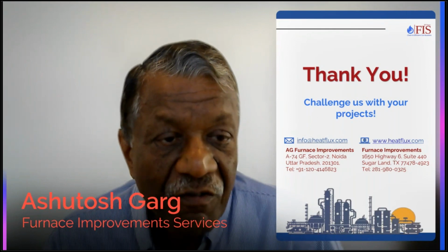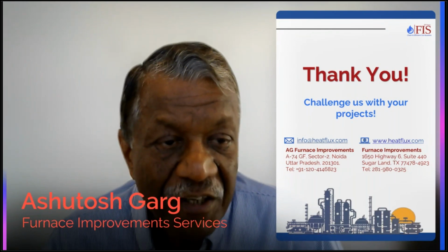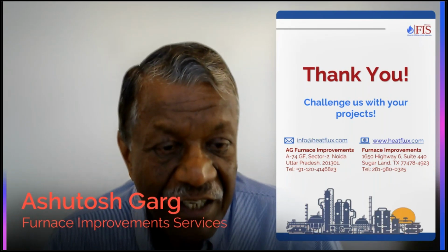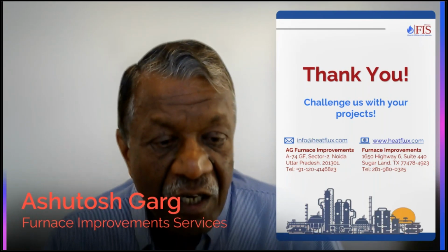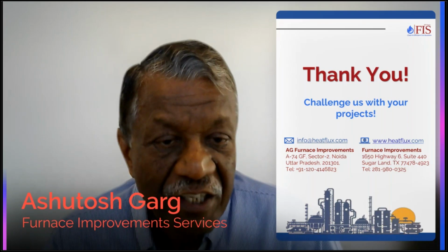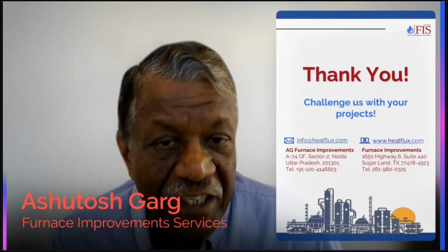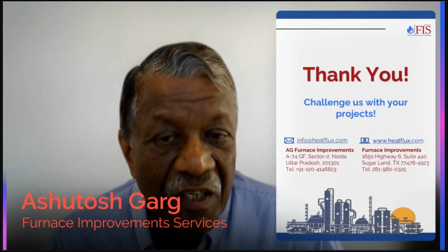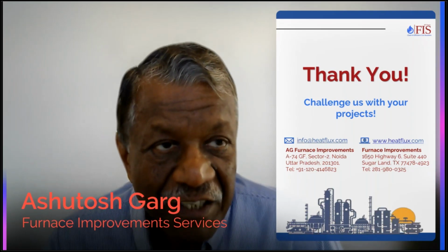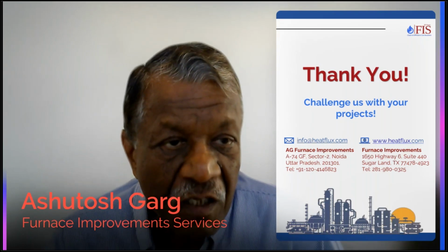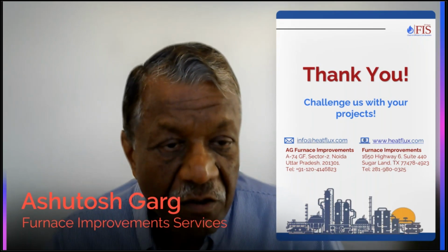I've done several webinars on inclined firing, and there are videos. We have done it on about 12 heaters now. It's very simple, and it does not cost much at all actually. You're just inclining the burners and you won't even notice about 3 to 5 degrees. That's how far the inclination is. So you can always call me.